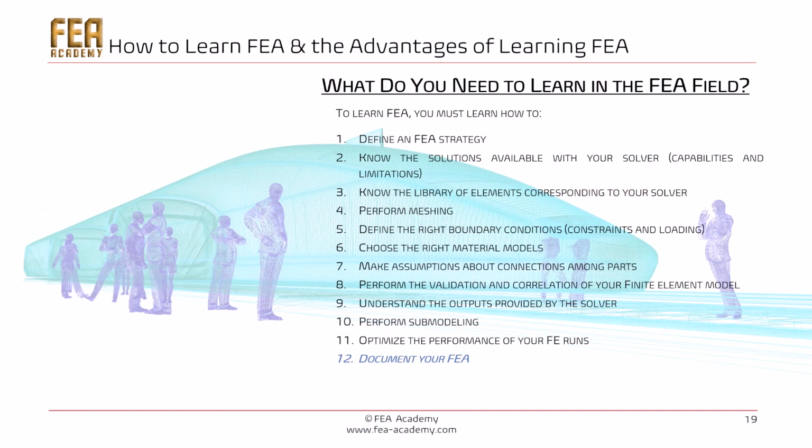You will have to learn how to document your FEA. Learning how to document an FEA is important because from an industrial point of view, an FEA and its associated results must be traceable years after the project is completed. Most FEA documentation today focuses mainly on the results, but these results are influenced by many parameters. So all the assumptions of the simulations should be documented also.